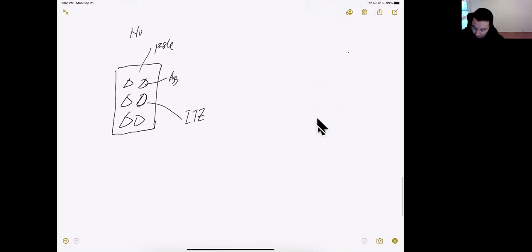For normal concrete, the weakest link is in the ITZ, or the cement paste. As a result, when the concrete has a crack, it will generate at the weakest link, which is the ITZ or the paste. And when the crack propagates, it will try to find the ITZ again. So this is the crack pattern we see for normal concrete.